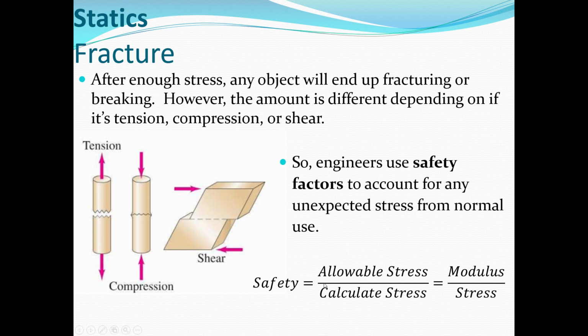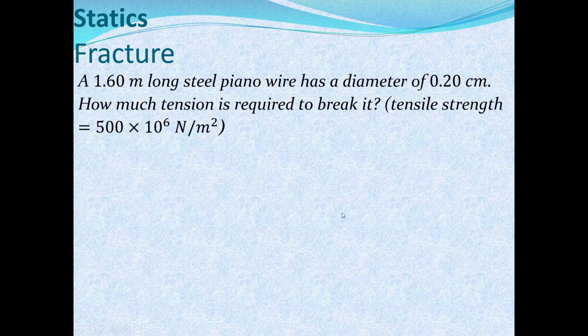Usually the safety factor is the amount of allowable stress over the calculated stress, or the modulus over the stress. I have some bonus questions at the very end of the PowerPoint, where you'll see how a safety factor can be used. Again, this is something for the engineering students.